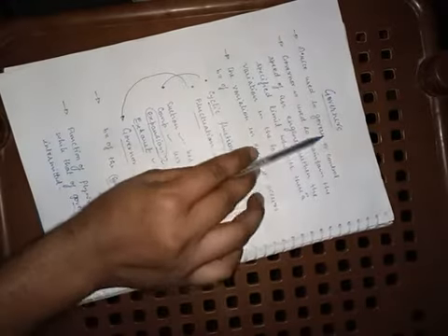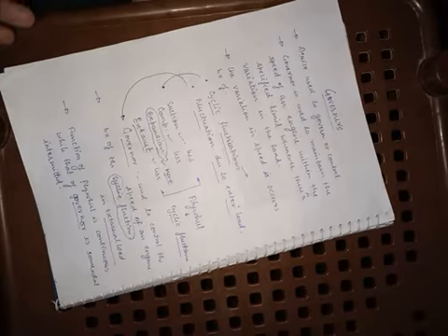So we are revising the things. Governor is a device used to govern or control. It is used to maintain the speed of an engine within the specified limit whenever there is a variation in the external load, assuming that you are moving on a road. As soon as a flyover comes and you climb over it, if you maintain constant throttle, the speed is going to decrease. Then to maintain the same speed, the governor communicates with the throttle, and the throttle adjusts itself according to the requirement.